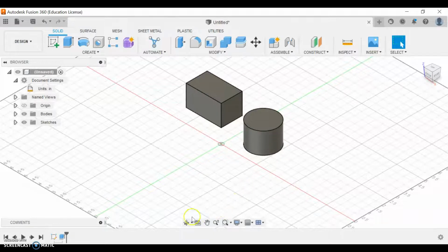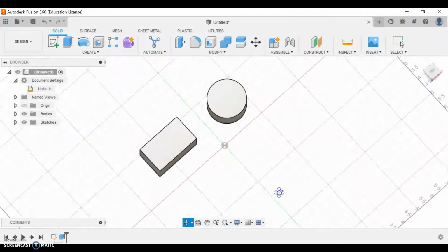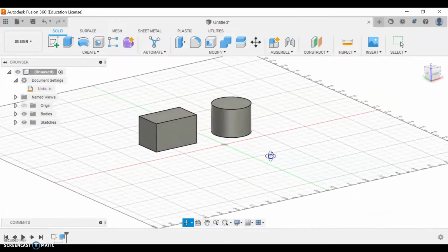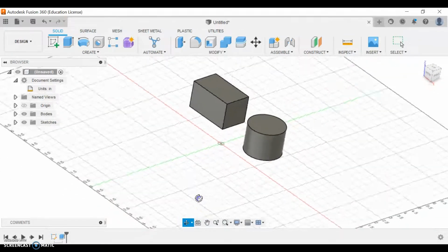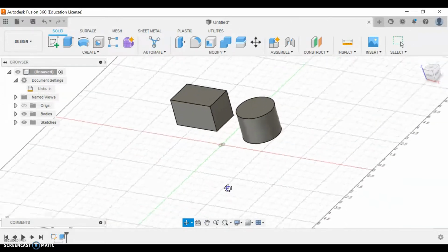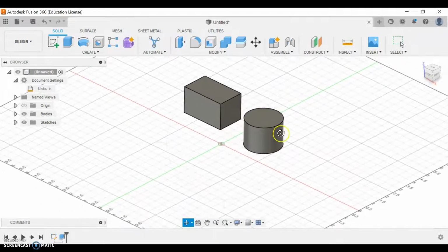Also, another useful feature for navigating, forgot to mention this one earlier, you can use orbit. If you click and drag here, it will let you change the angle, or the camera angle. And if you click on the side of the circle and drag, it lets you rotate. So that is a very useful tool when you're building larger structures. If you want to do just a normal mouse where you can select stuff, you'll go up here and press select. That's what I like to be on normally when I'm not creating a shape.